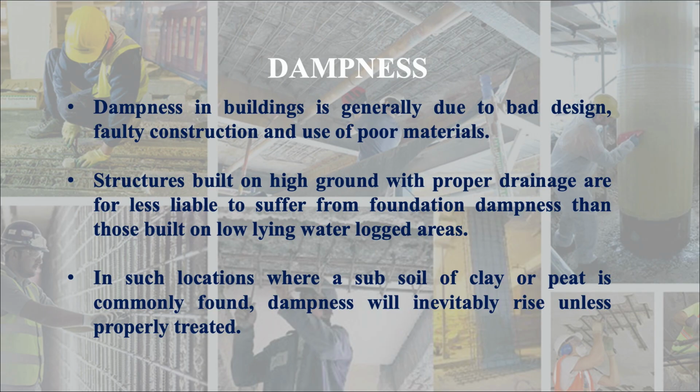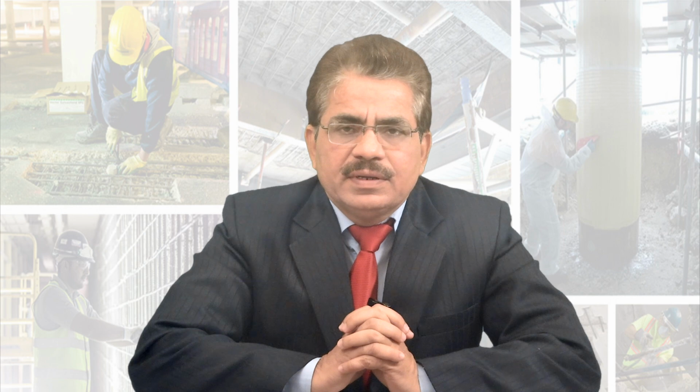In such locations where a subsoil of clay or peat is commonly found, dampness will inevitably rise unless properly treated. Means if your structure is located at locations where clay and peat soil is there, the problem of dampness will be more, because you know that clay and peat are fine grained soil and these soils are having number of voids less and does not allow water to move quickly.